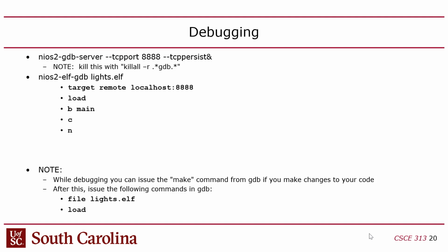So what that means is if you have a loop in your code and you put a printf in that loop, you're done. It'll brick the system, because it'll go through the loop really fast, and it'll overload the UART. It's really easy to do, and there's no warning. There's no graceful degradation. It just craps out and bricks your system.